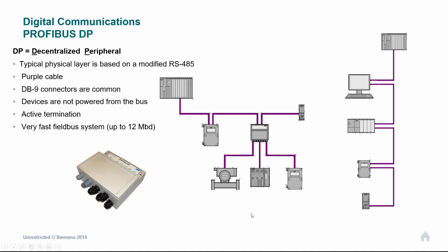What I would say is Profibus DP really isn't designed for hazardous areas. I know we can get around it and we can do it, but it's really not what it's designed for. It also doesn't like water. If you start to get condensation in your junction box and you're affecting that plus or minus 15 volt signal, you'll start to cause issues across your whole network, and that could be the junction box on your instrument not being sealed properly with the wrong cable glands. So yes, you can take it out into the field, but be careful.